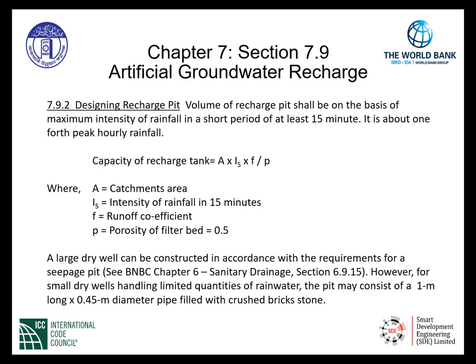Designing recharge pit. Section 7.9.2. Volume of recharge pit shall be on the basis of maximum intensity of rainfall in a short period of at least 15 minutes. It's about 1/4 peak hourly rainfall.